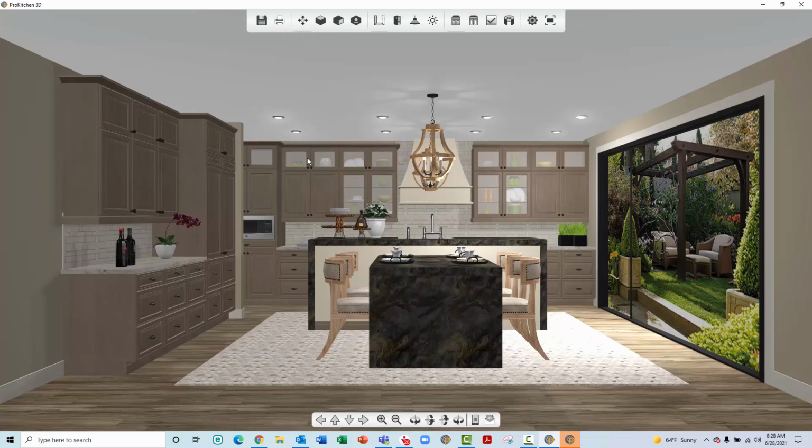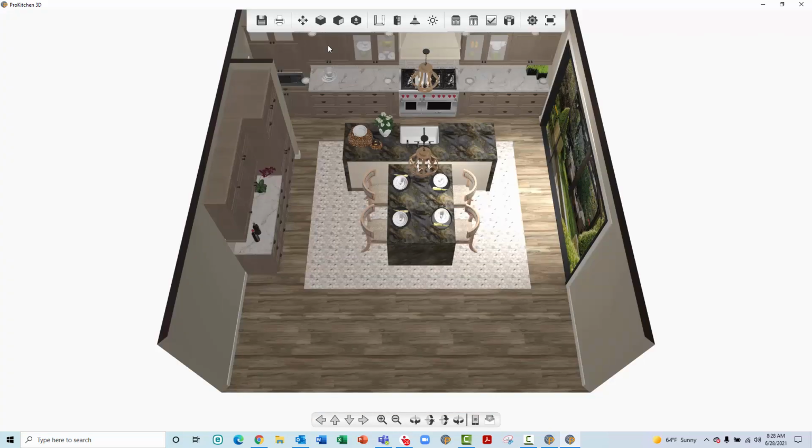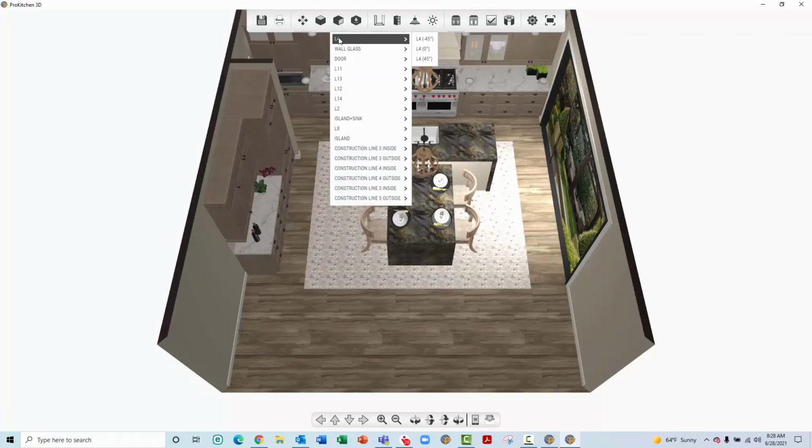Use the Camera Control tools to turn the bottom toolbar that consists of your Shift, Rotate, and Zoom tools to change the camera perspective on or off. Use the Top View tool to switch to a 90, 60, or 30 degree top view angle of your design in 3D. Use the Front View tool to switch to one of your elevation views in your design in 3D at -45, 0, or 45 degrees.